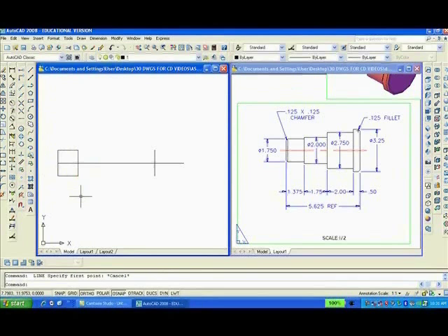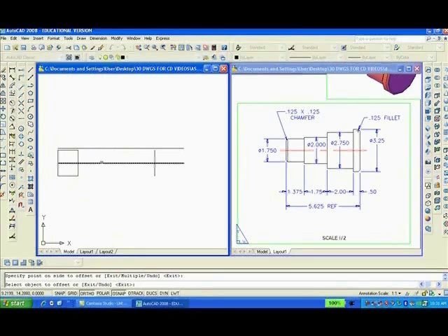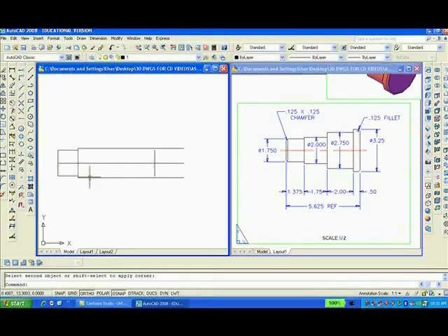Next I'm going to offset O, enter, 1, enter. Goes up, that goes down. And I can fillet it, F, enter, that, as well as that. And I can offset O, enter, 1.75 from here to there. And I can fillet it, F, escape, F, enter, escape, F, enter, with a radius 0, these two lines.